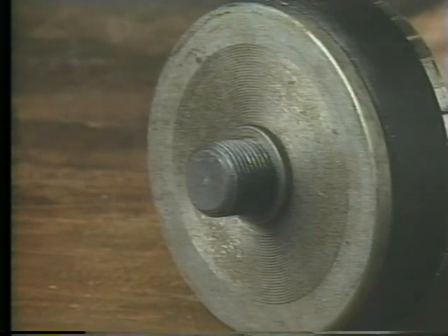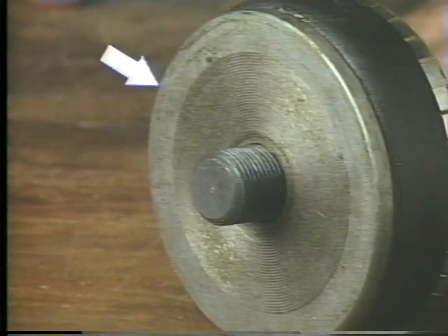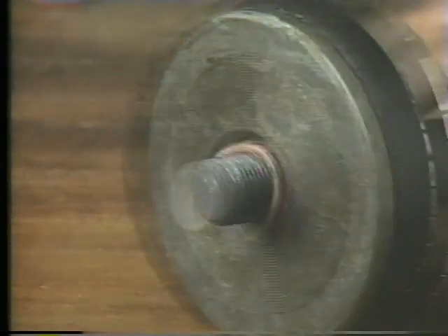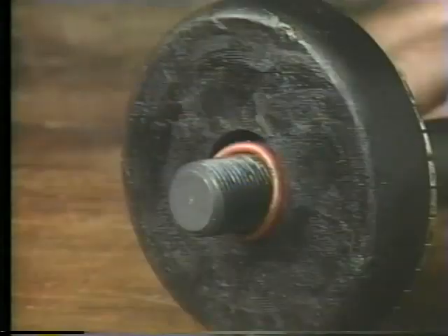Between the two cup assemblies is a rigid metal disc called the piston flange, which gives strength to the piston assembly. Inside the piston flange is an O-ring, which provides a seal between the piston assembly and the piston rod. If the O-ring is damaged or worn, it is replaced when maintenance is done on the actuator.